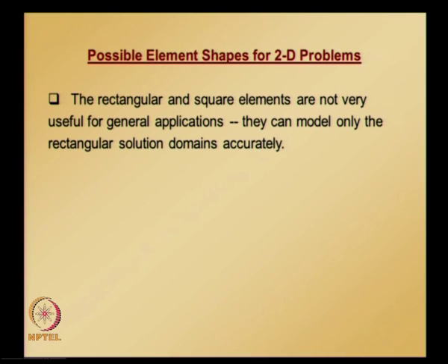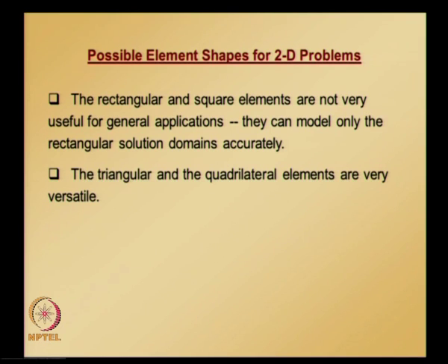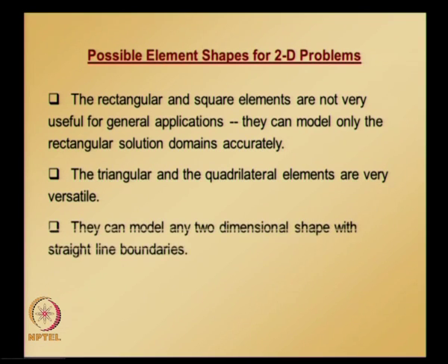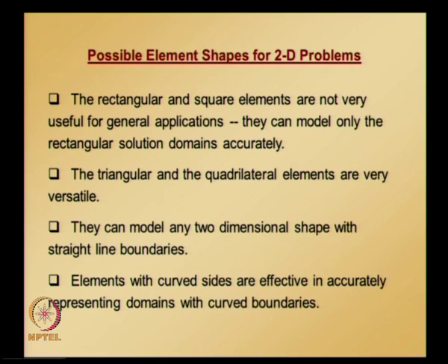They can model only rectangular solution domains accurately. The triangular and quadrilateral elements are very versatile. They can model any 2 dimensional shape with straight line boundaries. Elements with curved sides are effective in accurately representing domains with curved boundaries.